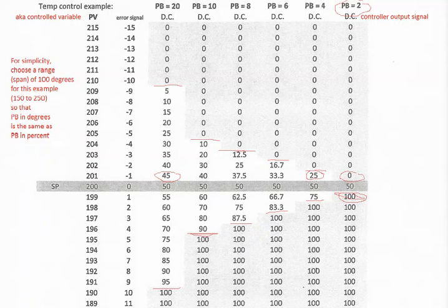It basically takes as drastic an action as it can to maintain your set point without spilling over into causing oscillation, where it's too drastic, so that the system's own inertia causes these oscillations where you're slamming it in one direction and the other too severely.